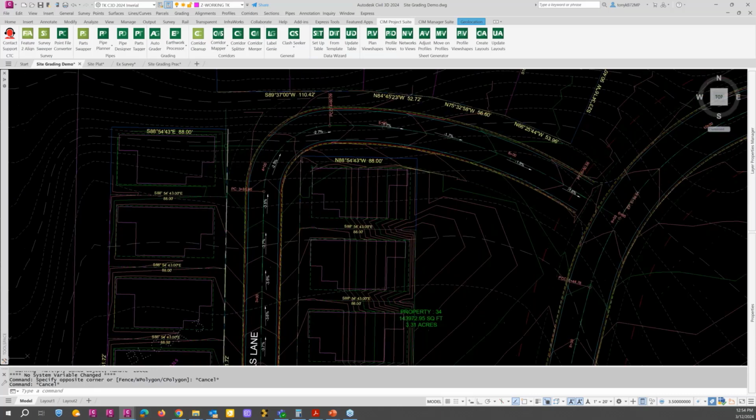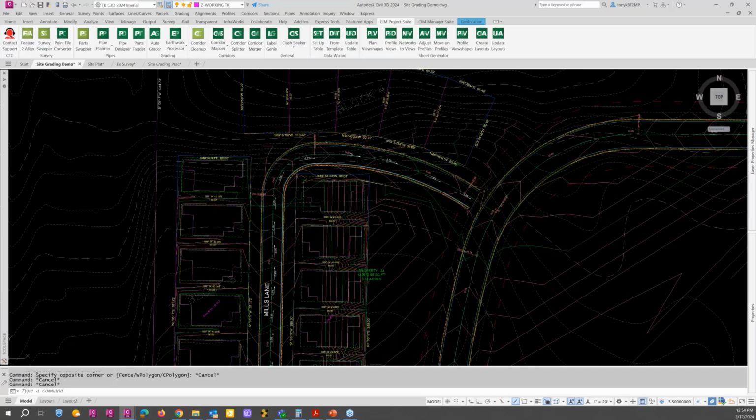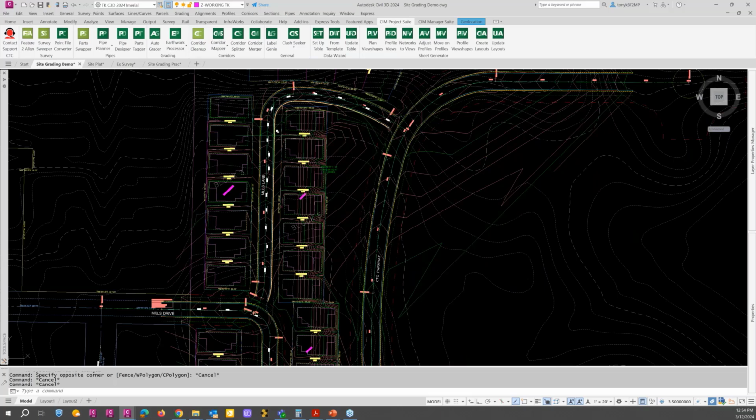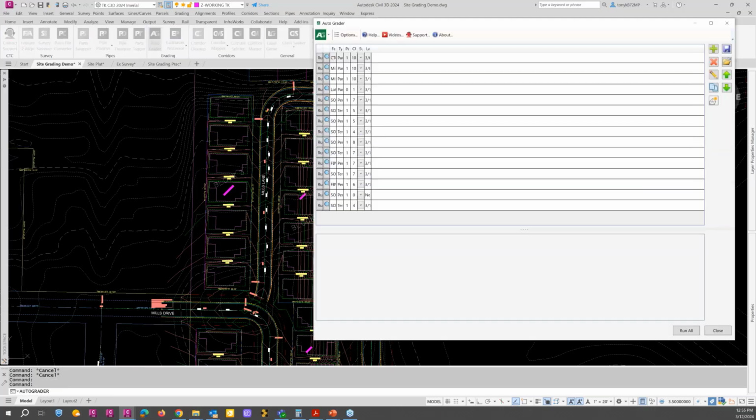And again, to make these feature lines, I want to show you this too. I use that right here. We don't have a sidewalk for these. So after I created my feature line, or the road right here, I pump those out to where they match with the lines. And I don't need those feature lines in my break line set anymore. So I can get those out of there by simply, I could delete them.